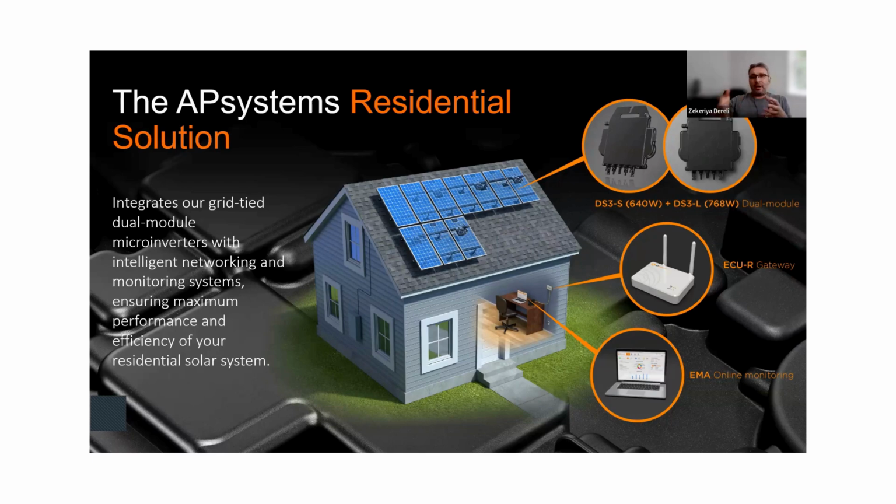The way it goes is you basically mount the microinverter right on the rail. It's really easy to attach. There's a bracket on top, as you can see. It just slides into a slot there with a screw, tighten it, good to go. There's not really any other attachment needed. Then you would wire PV modules to the inputs of the microinverter, and you would have a trunk cable for the AC.